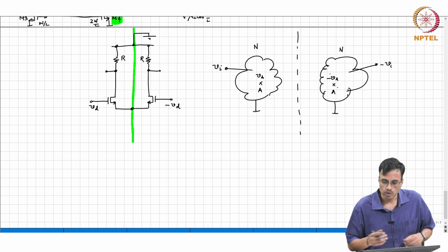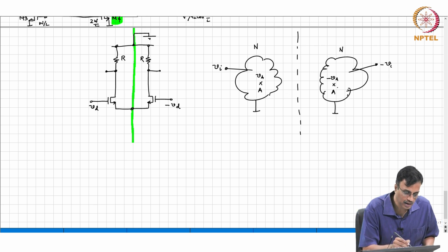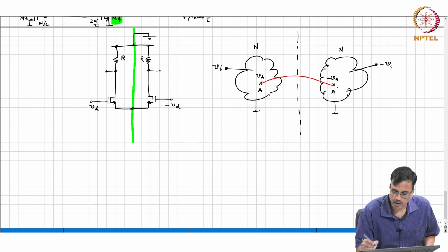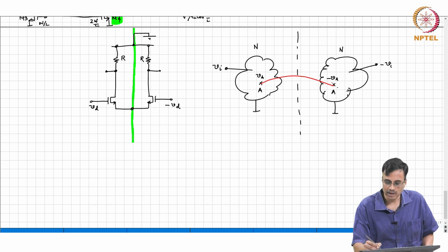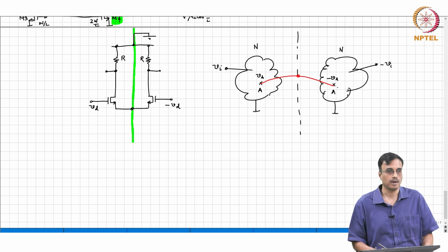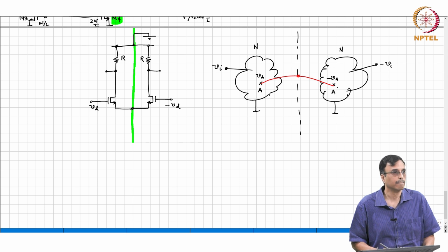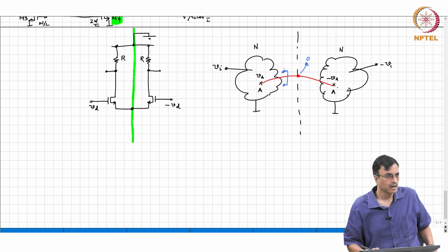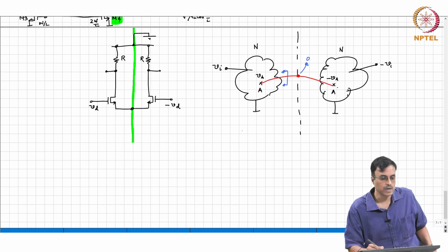Okay. So, if I now join this node to that node, what comment can I make about that voltage? If you look at the Thevenin equivalent at point A, what will the Thevenin equivalent be for the circuit on the left? Come on, quick people, there will be some.